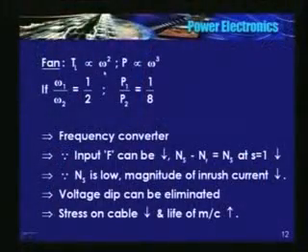What sort of torque speed characteristics do these loads have? TL, the load torque, is proportional to the square of the speed. TL is proportional to the square of the speed. So look here, see here. For a fan type of load, TL is proportional to omega square. So therefore power is proportional to omega cube.